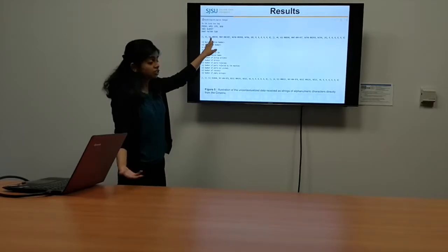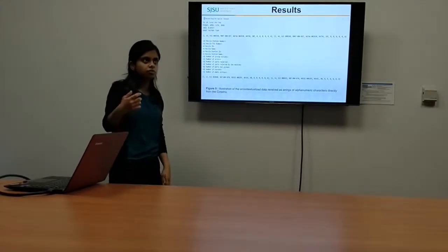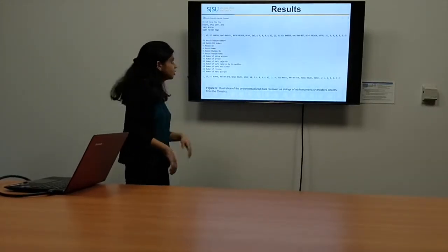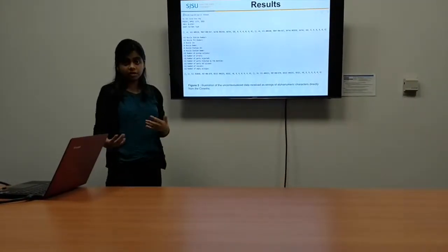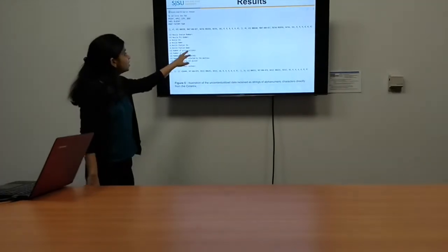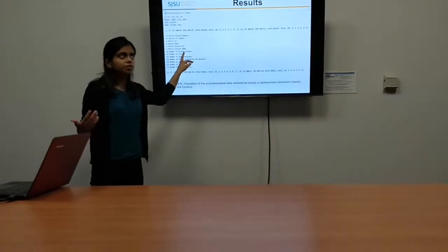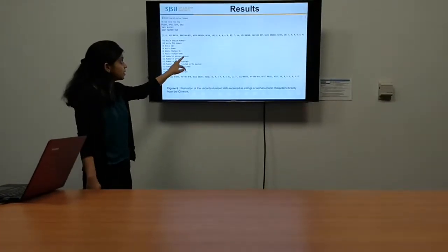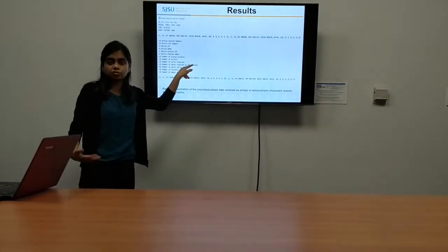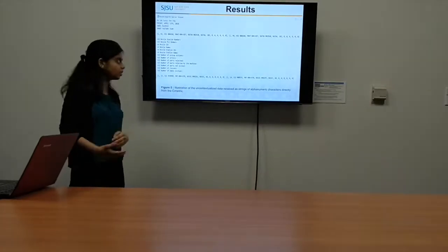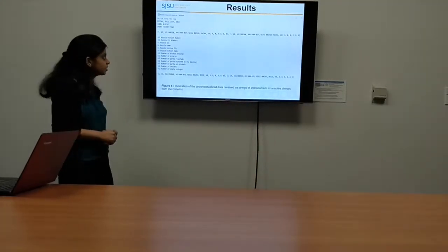The third, S31, actually means the nozzle ID, which is again a part of traceability. And station ID again is a part of traceability. Station name again a part of traceability. And then comes the production interesting data, which is the pickup actions. As you can see, we had 102 pickup actions for one of our nozzles, which is a huge number from the manufacturing perspective.